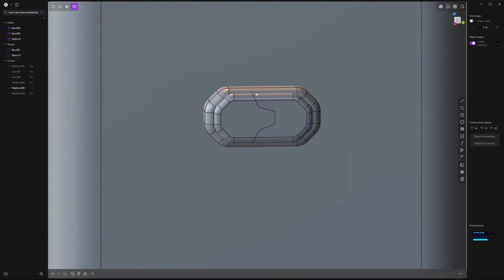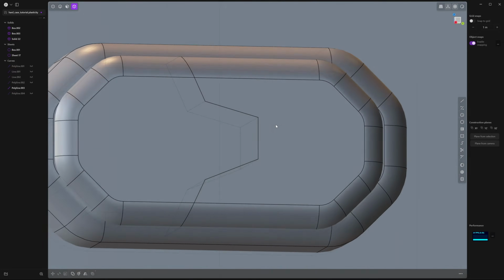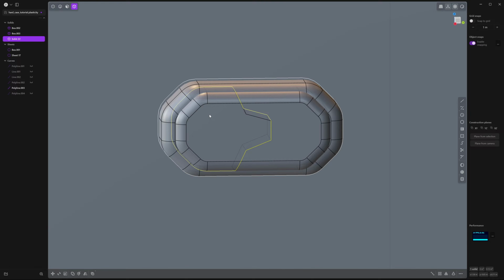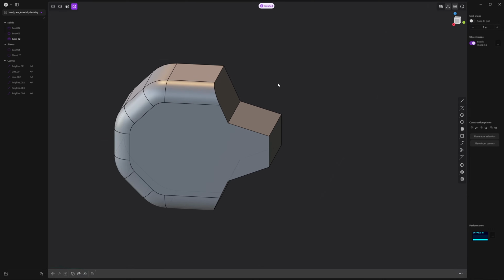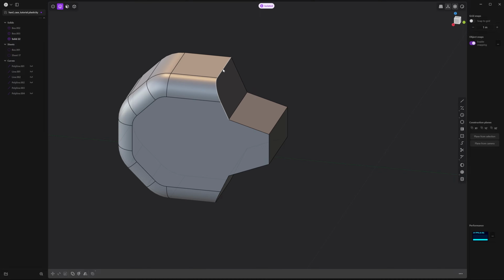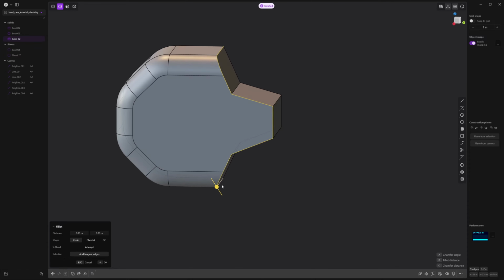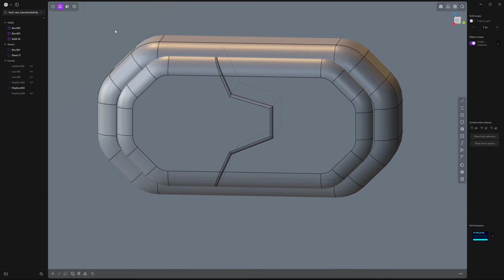Great. So now you have two pieces, but maybe you want to create a little bit of a fillet or a separation so it doesn't look too perfectly aligned. So let's select one and press period. That'll let you isolate an object so you can just focus on it. And we're going to select these edges by holding Alt and clicking them. Shift click to add any additional lines. And then we're just going to give it a slight fillet. Right click to accept. Press period to exit isolation mode.